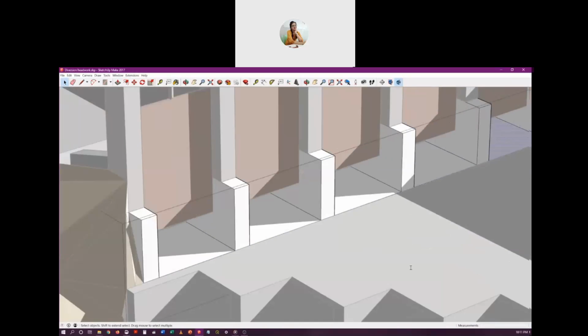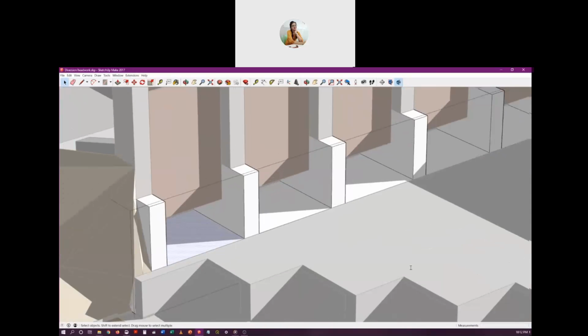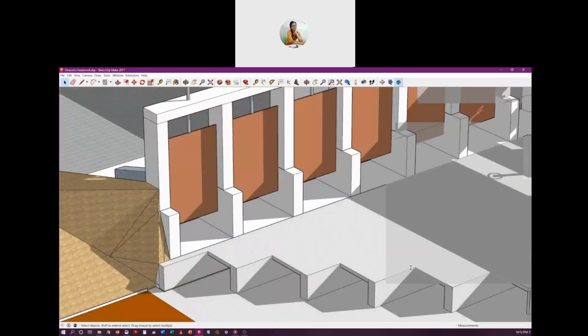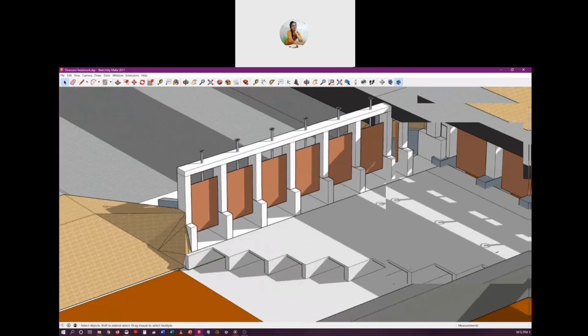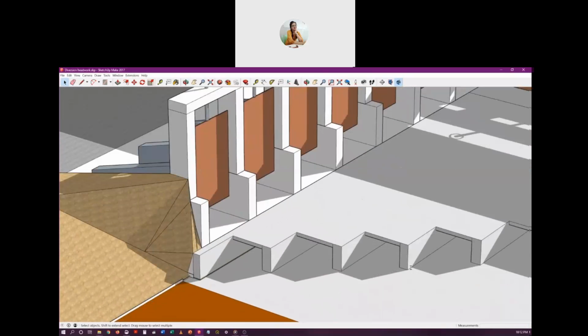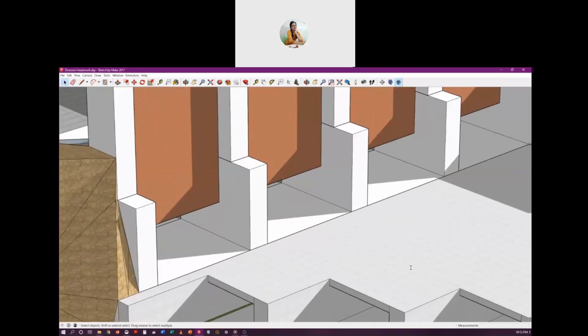If the riverbed itself is much lower, suppose 2 or 3 meters lower than this level, then these kinds of silt excluders are not needed because the lower part is already much lower than the sill level. Therefore, the sediment which is carried by the lower portion of the current will not be able to enter these gateways.